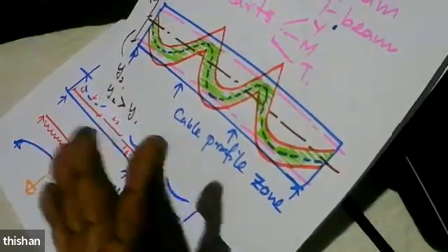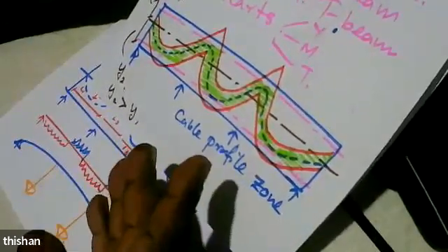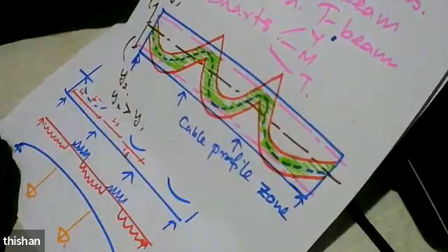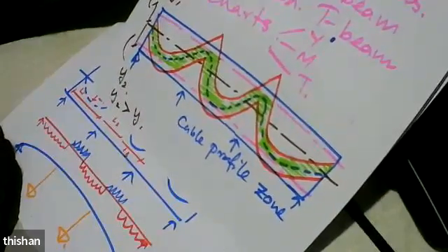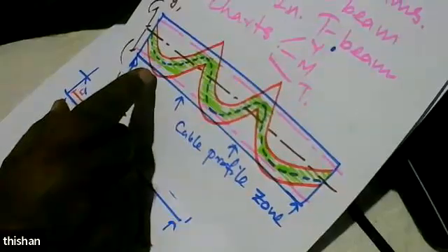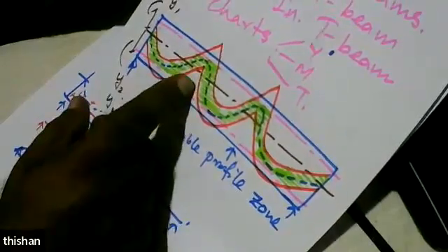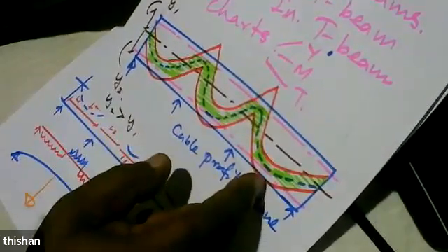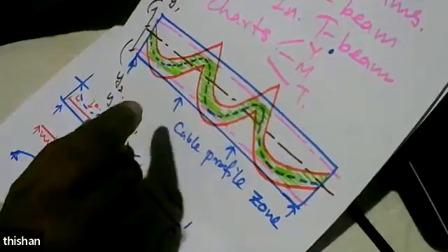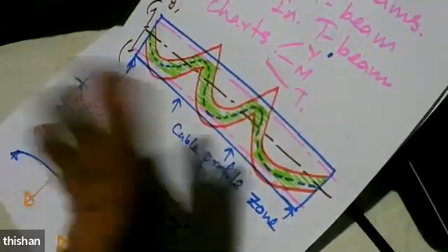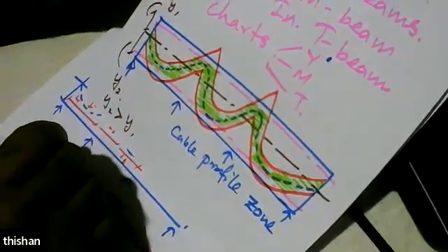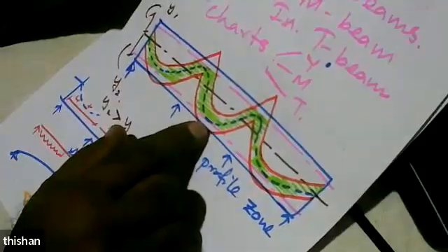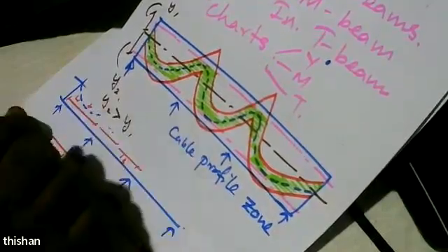Because before getting that, you have to draw the moment diagrams at each critical section, that is here, and then see which pre-stress will work. And sometimes here you will find the pre-stress has to be 18,000. Here you might say 20,000. Here 22,000, and then here again 18,000. This 17,000. Then you will say, okay, I'm going to select 22,000, because we always know the minimum will not work, but a higher value can always. So out of all these, the highest is given here as 22,000. Then we might select 22,000.